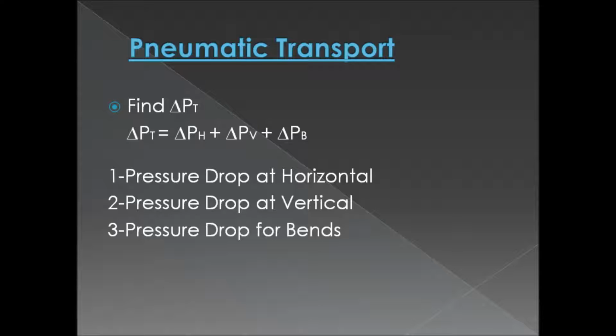The advantage of dense phase transport is low air requirements, which generally means a lower energy requirement. The resulting low solids velocities mean that product degradation by attrition and pipeline erosion are not major problems.